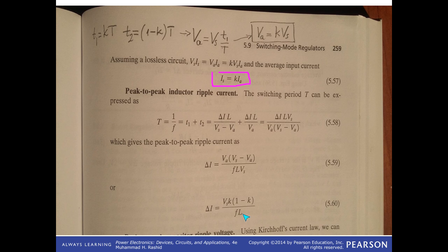That's why people use high frequency here, in order to reduce the size of the passive elements, and also in order to reduce the fluctuations, frequency is increased.